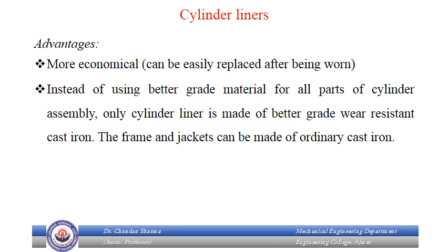But when we go for cylinder liner, we only need to have better grade material for the cylinder liner, and for the remaining cylinder we can have an ordinary cast iron. So instead of taking the whole material of superior quality, we can only use cylinder liner of superior quality so that when worn it can be easily replaced.